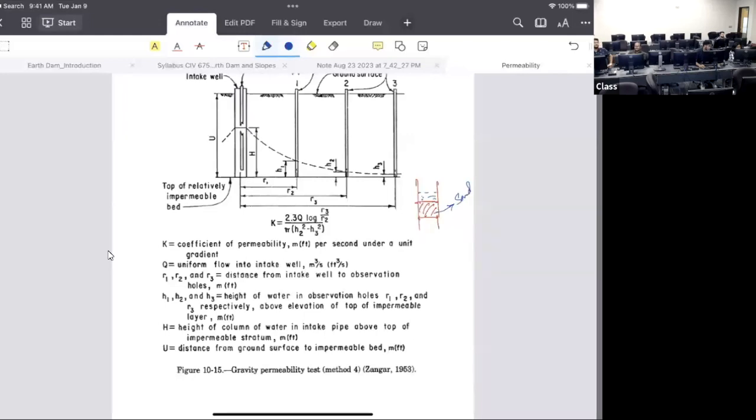So it's going to be very difficult for us to get any data, right? So what we should do, we need to keep adding some water, so it will keep a constant head there. Whatever the flow is going out, we have to add the same amount of water from the top, so we can have a measurement in the sand, right?